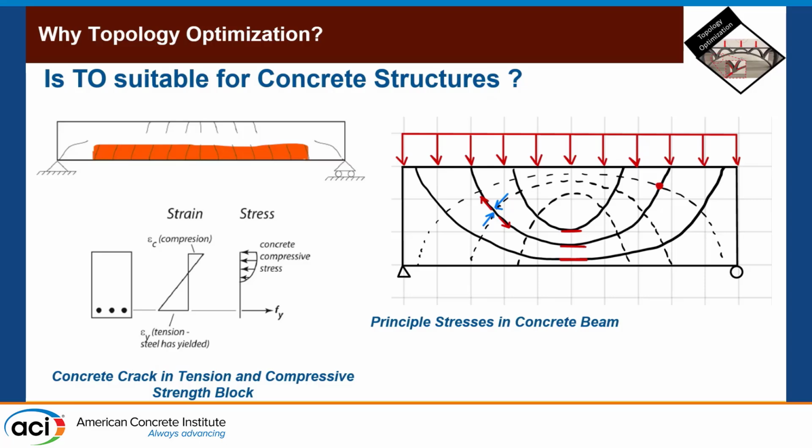Concrete, by nature, cracks in tension, so the reinforcement can carry this tension. You can see here the hand drawing of the compression line and the tension line. We are trying to envision a system where you print the compression line and you reinforce the tension line, and you have anchorage between them. You can see here this depth of the concrete actually cracked, and the main reason in reinforced concrete is to hold the reinforcement and have compatibility with the cross-section.